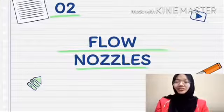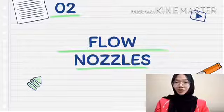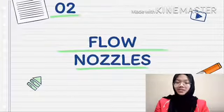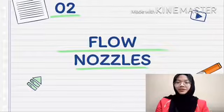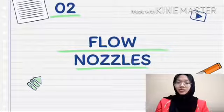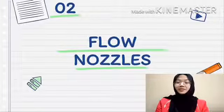In this slide, I would like to tell you more about flow nozzle. A flow nozzle is a device used to measure the flow rate of fluid in a pipe or conduit. A flow nozzle consists of a cone-shaped passage that creates a partial blockage of the conduit. The flow rate is determined by measuring the fluid pressure before and after the flow nozzle. Flow nozzles are also used to gather data, and to improve manufacturing performance and tolerance to extremes in process.